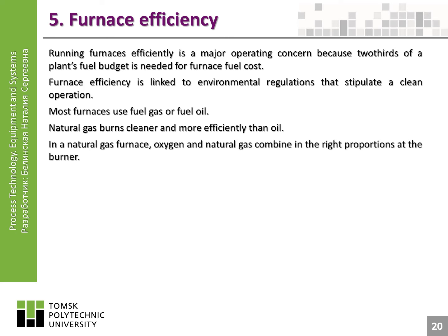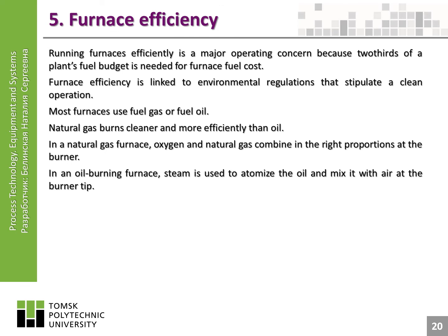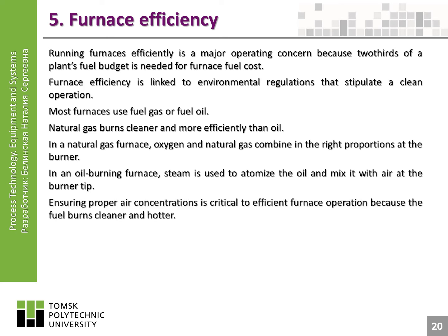In a natural gas furnace, oxygen and natural gas combine in the right proportions at the burner. In an oil-burning furnace, steam is used to atomize the oil and mix it with air at the burner tip. Ensuring proper air concentrations is critical to efficient furnace operation because the fuel burns cleaner and hotter.